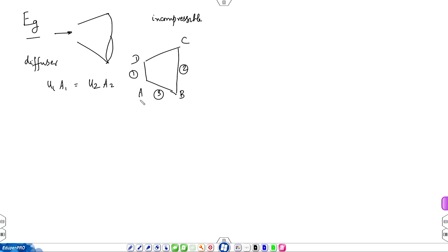So, you make a tube out of a mesh, and there is flow taking place inside the mesh, then flow can come out through the mesh. So, U dot n is not 0. So, we are talking about an impermeable solid tube, solid in the sense there are no pores in it. So, impermeable, so, then U dot n normal velocity is 0, that is a boundary condition.